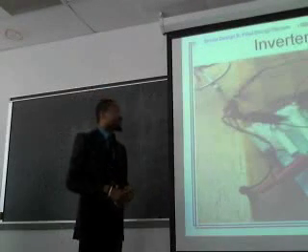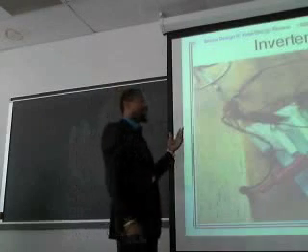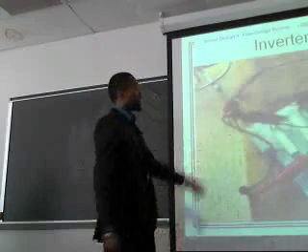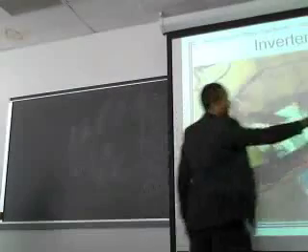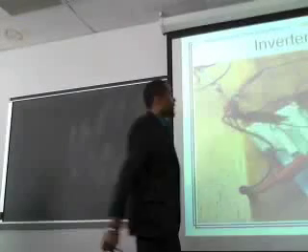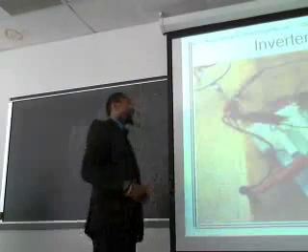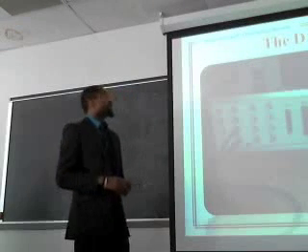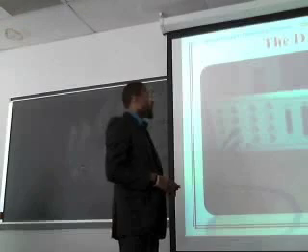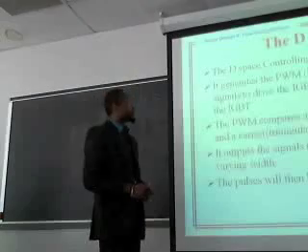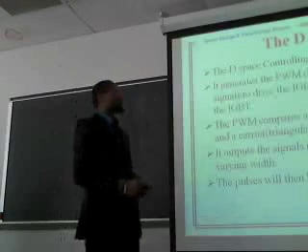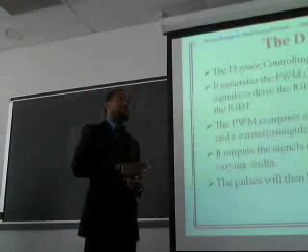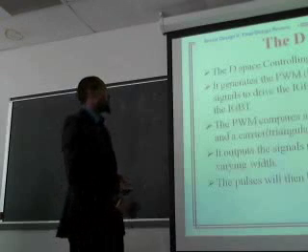Also now we have our inverter circuit. After converting the AC current to DC, we need the inverter circuit to convert it back to AC. That's what we build. You can see we basically have our gate driver right here. But this is basically the inverter circuit. We're going to show you the overall circuit and the result which we have after designing the whole system. And this is the dSPACE, which we use to display and measure. And the dSPACE controls the whole system basically. So you have the power to do whatever, change the frequency or the amount of power you want in the system. So dSPACE helps us to do that.